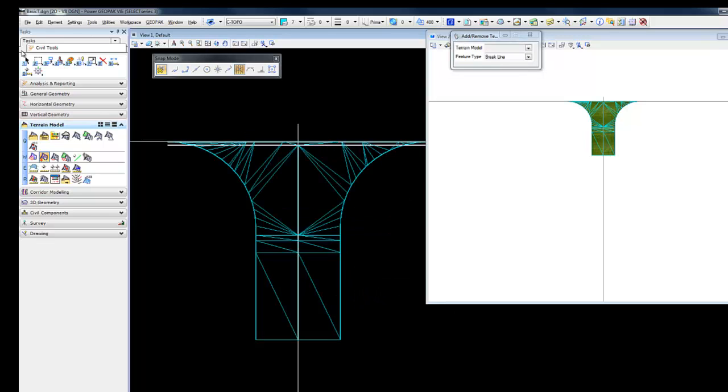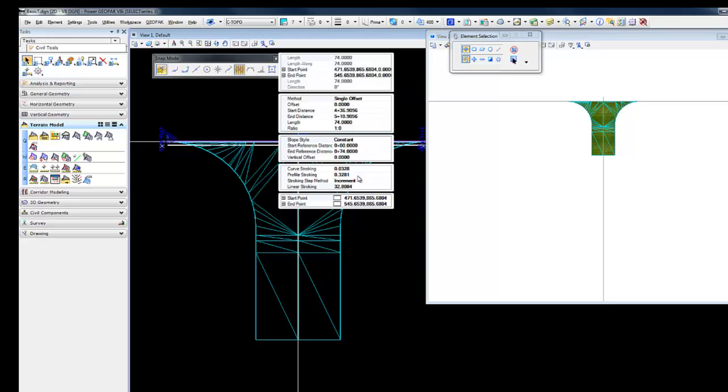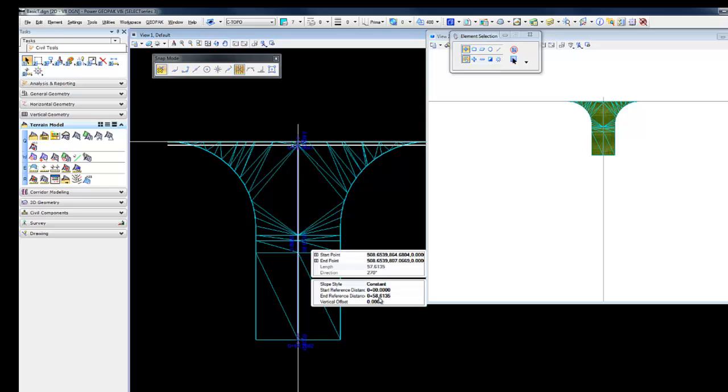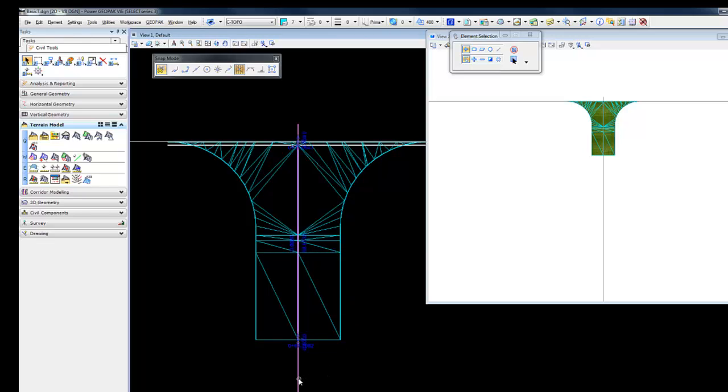Next, we can set up stroking along these elements. We do that by going into the properties and changing the stroke value. In this case, I'll set it to 5 feet. Typically on the center line, we won't have this option because we've set a constant elevation. However, after the cell's placed, we'll have the option to change the stroke value along that line. We can also opt to change the stroke value along the arcs if we want. Typically 0.03 is a good place to start.